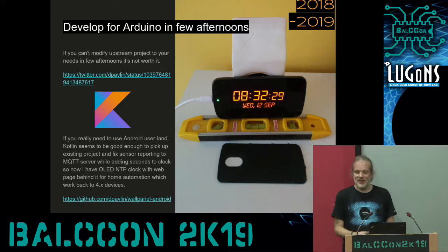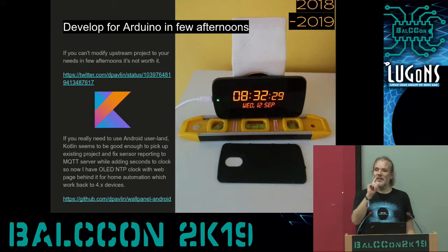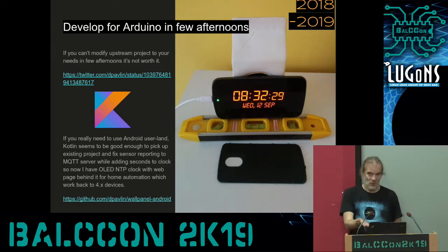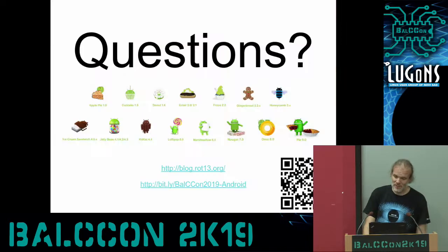And this was the reason I decided to change the software to something which can actually move the clock over the screen so I don't get the burn-in. And another interesting tidbit, if you look at this picture, the back side of the phone is actually removed. That's because most Android phones are not designed to be always on, especially not designed to have the screen always on. This cell phone, a Galaxy Nexus, the original Google phone, overheats if you don't remove the back cover and have the display turned always on. And this is an AMOLED display, so it doesn't draw power other than for the pixels which are actually lit. Just words of warning.